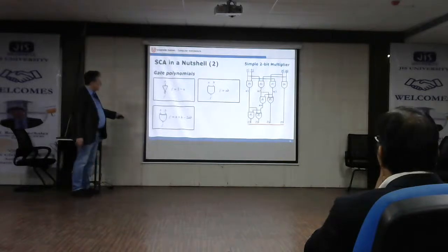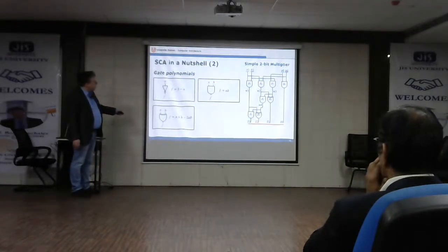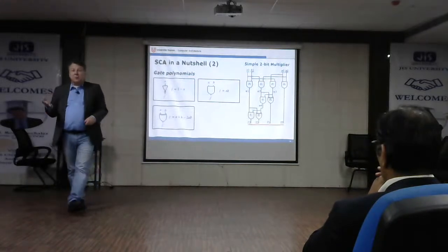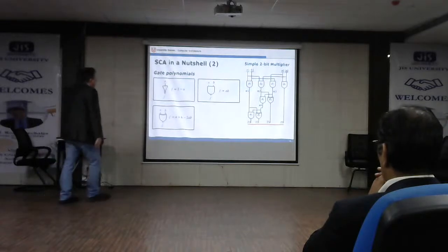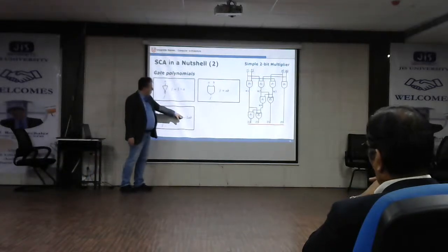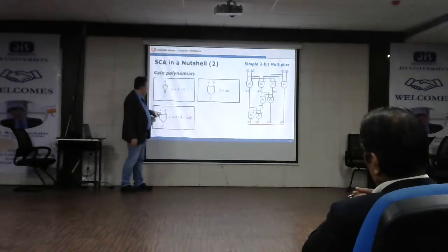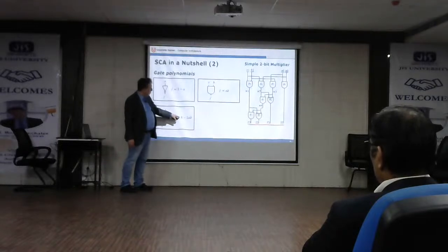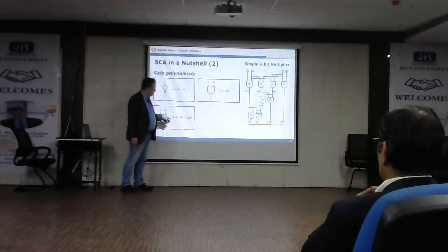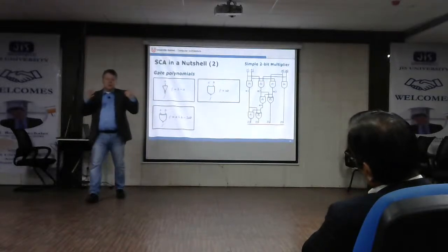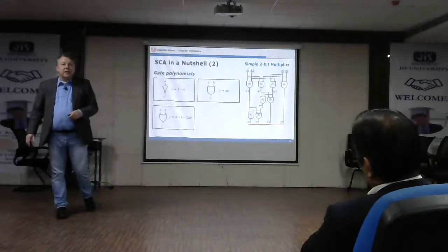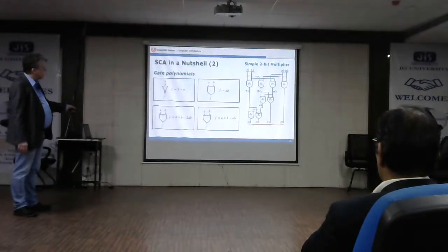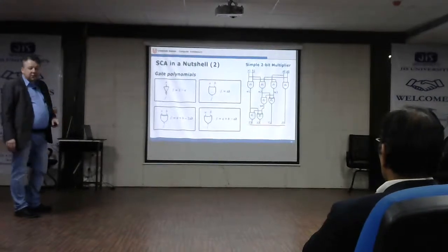For the XOR gate it is a plus b minus 2ab. And here it's important that this is not a Boolean formula, but really a polynomial description. So if you enter 0 for a and b, it is 0 plus 0 minus 2 times 0, which is 0. So that's exactly the value of f. And if one of them is 1, it's 1 plus 0 minus 0, it's 1. And so you can directly see that this is the correct functional behavior. And the same for the OR gate. So this means we have these kind of polynomials that represent each of the internal gates.